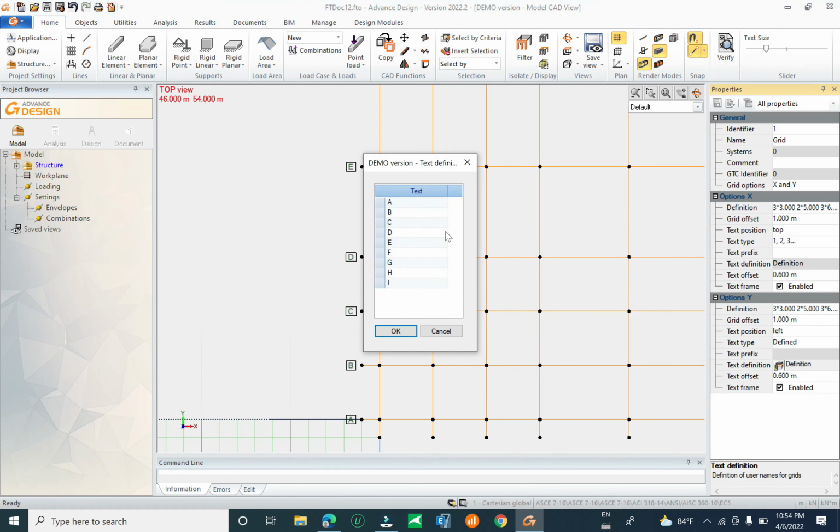It's appear, disappear, appear. Okay, now you see here, this is the last point which I create. Now click on it, and you can press the key. And you see here, this is the label, the grid line we just create for the example, and we will continue to another one. This is for the measurement or the dimension line.